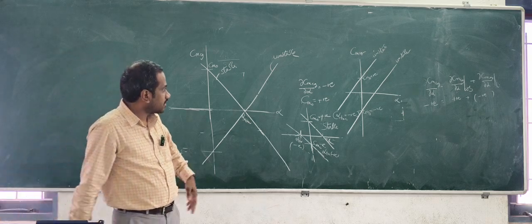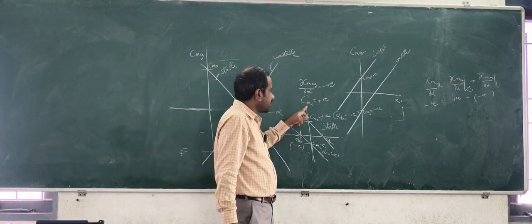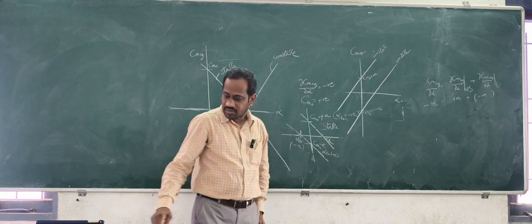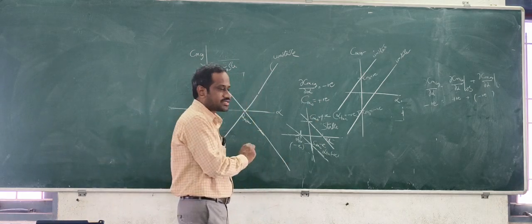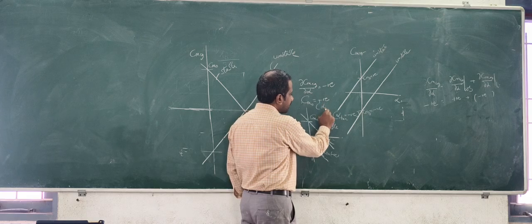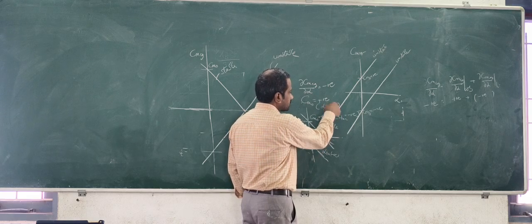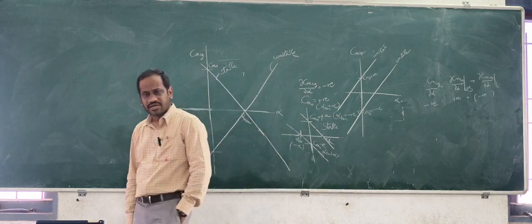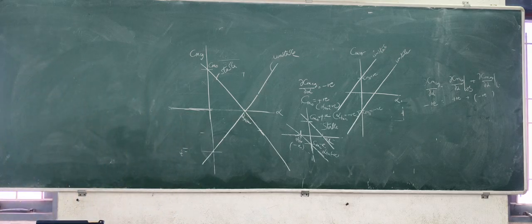Though we keep it under longitudinal static stability, Cm naught positive is a desirable condition for alpha trim positive. The balancing will take place at a positive angle. That is a desired condition. So that is why it is also kept under the criteria. Follow that rule also. Otherwise, strictly speaking, the stability criterion is dCm by d alpha should be negative. Cm naught positive is not the primary criteria. It is a desirable criteria.